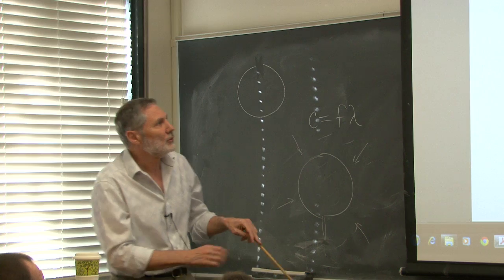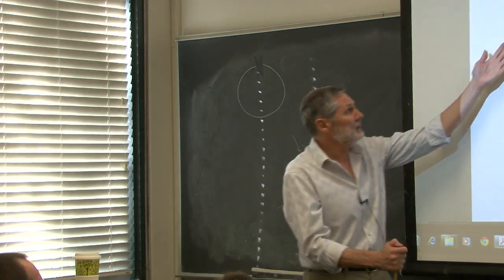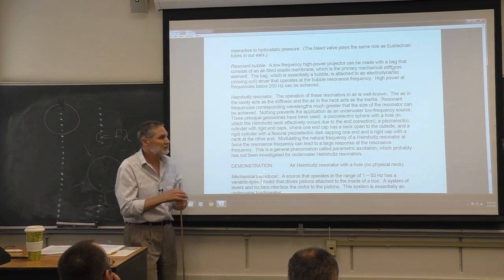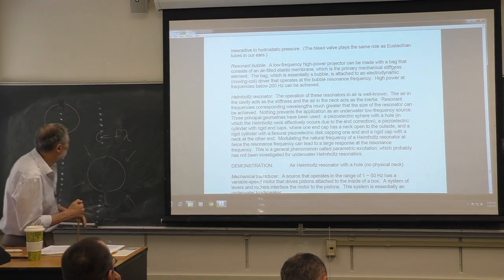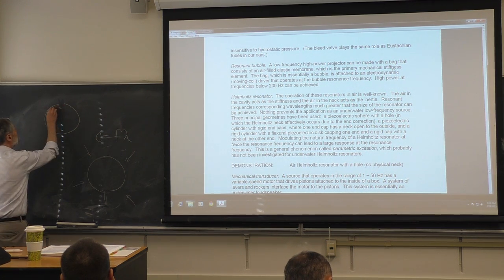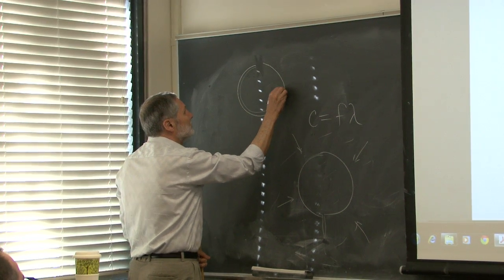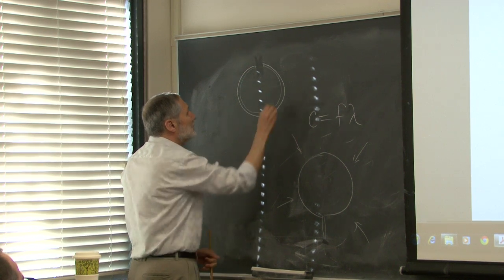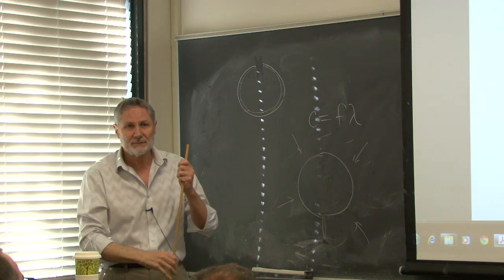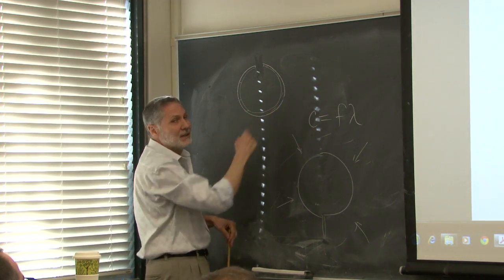So it's a natural candidate for low frequency sound because the wavelength is typically much bigger than the size. That's what we want. People have done different things. They've taken spheres like this with a hole in it, with piezoelectric material, and they drive it. You can imagine it's plated on the inside and outside.